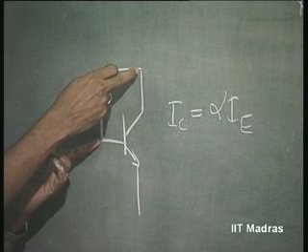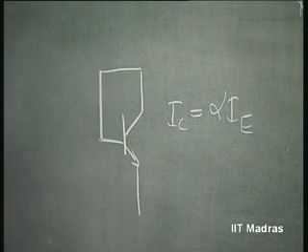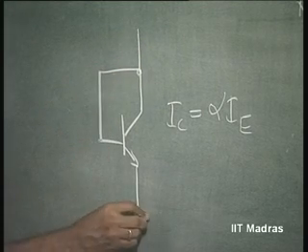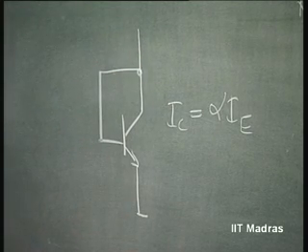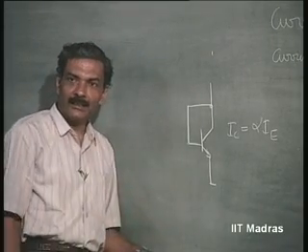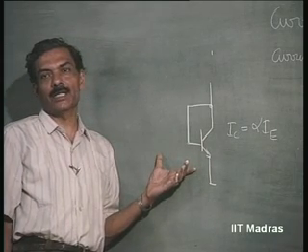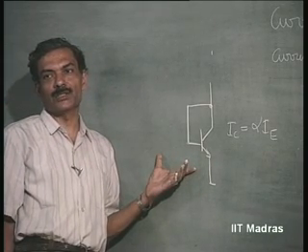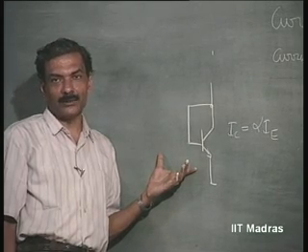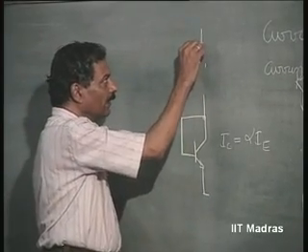Up to this point, we said the transistor is in the active region. So, this is a very nice structure. Externally, this looks like a 2-terminal element, which is nothing but a diode, but internally it is acting like a transistor. This is the most popular structure used in integrated circuits for biasing, a transistor connected as a diode. Let us see what happens when I pass a current through this.